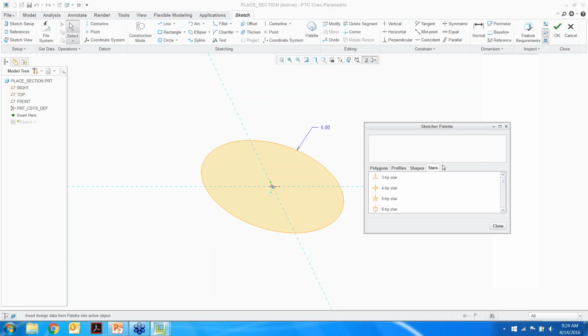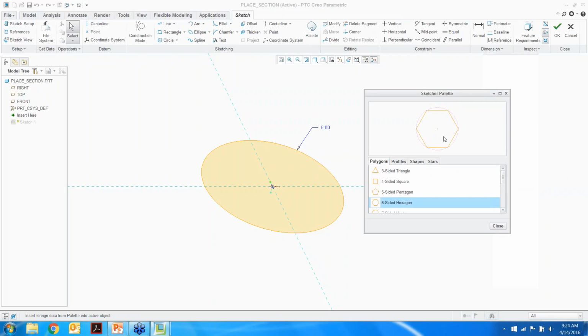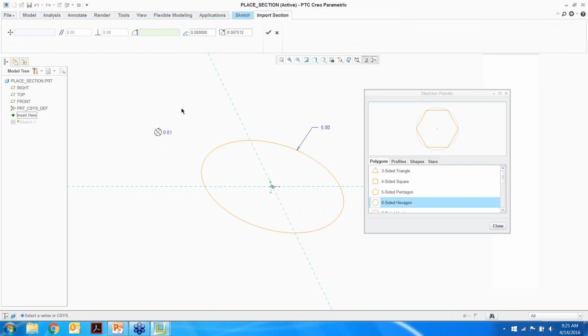And again, if you set the Config.pro option that we mentioned earlier, then you can add more tabs onto here. So you can have multiple entries of that Config.pro pointing into different directories, and it will automatically add them onto here. The way you work on this one, let's say we want to bring a hexagon over here. This window right here at the top is just a preview, so you can see the shape that you're bringing in. If I want to place this section, you want to drag it and drop it somewhere over here. Now, as you're dropping it, I know I want to place it in these references, but right now I want to place it a little bit farther away. So I'll place it right here. Notice that my scale is pretty small, so I'm going to change this scale to about 5.